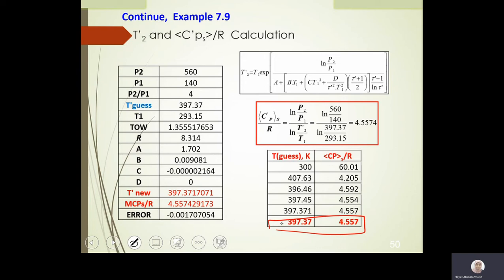If you remember, if it was water and we use the thermodynamic tables, we already agreed in chapter 6 that the properties of liquid, if it is compressed, as an approximation, we take the properties of liquid for the subcooled state. Does it make sense here? If I have a pump and the inlet was liquid, the outlet was subcooled, then we said that at subcooled, at the given temperature, you will go and get the liquid property.